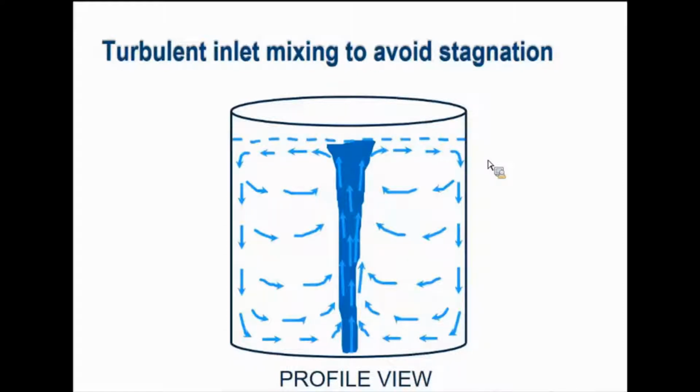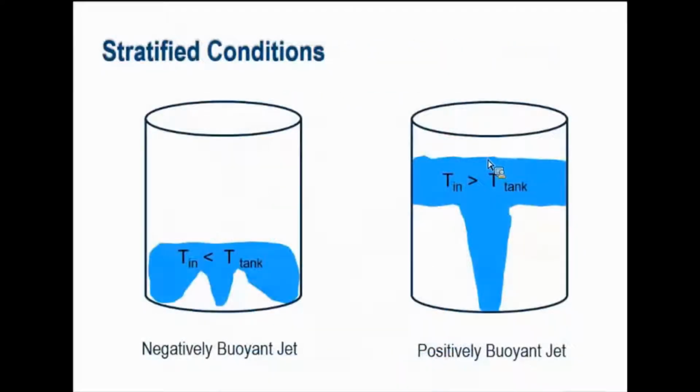Maybe there are different types of inlet and outlet valves on the pipe. There's duckbill and different proprietary versions that allow water to go one direction and ensure that there's turnover in a tank. Or there are physical mixers that could promote the same kind of behavior. But keep in mind, a really well mixed tank may just be really well mixed old water if it's hydraulically locked out or something. You could also, with the tank, have mixing conditions that are temperature relative.